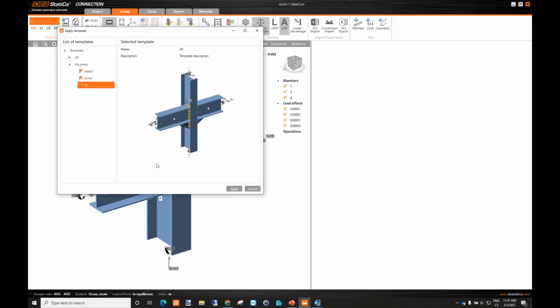For example, beam number 1 has a declination of 1 degree, and the original has 2 degrees. In this case, you would not be able to apply the geometry and the operations on the other joints. The geometry must be the same. The beams can be different. For example, the height can be 200 and the new one 300. It will appear here, the template, but the geometry must be the same.